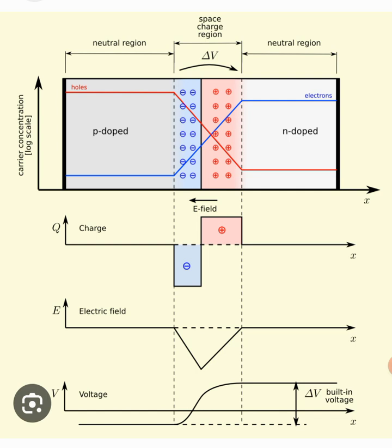Now look at the charge carrier concentration in the log scale. As shown in the red, there are majority carriers in the P type semiconductor, which are holes. There are plenty of charge carriers and their carrier concentration decreases in the depletion region, it goes down, and in the N type semiconductor material it is obvious that the holes will be minority carriers.